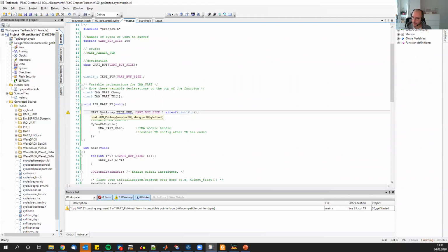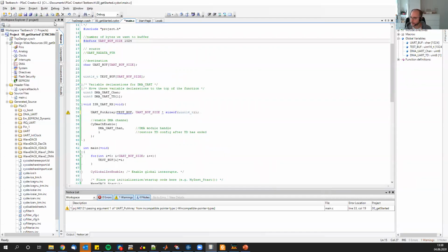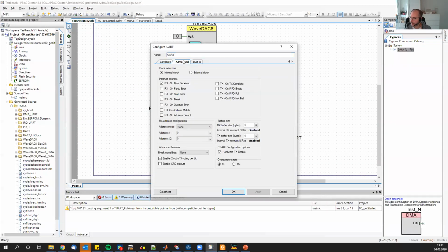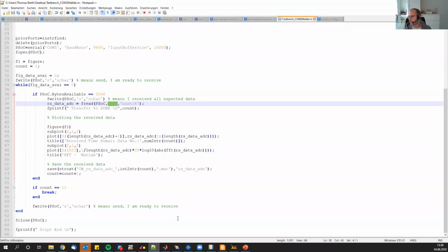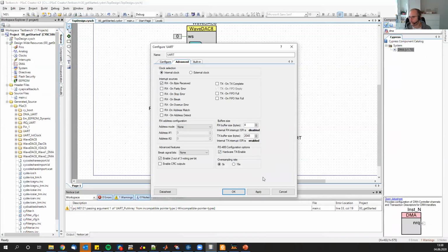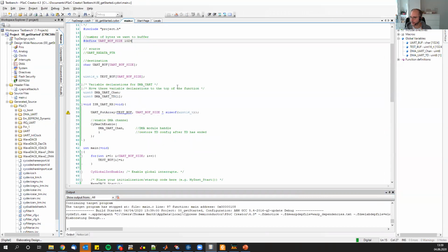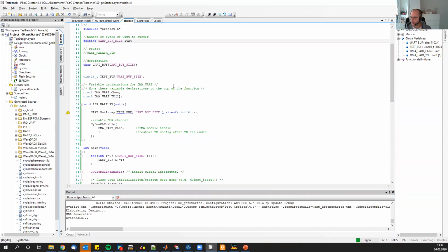It's an 8-bit byte count value, and we want to transmit later on this size, right? So this will not fit. My recommendation here, no matter what, is to increment this buffer size anyway to at least this size. This is the number of bytes we're expecting, so why have the hassle of dealing with that? Simply say for my UART module, I have this as a buffer size. Let's see if this will change the API, because otherwise this might be a problem for you guys to implement that.